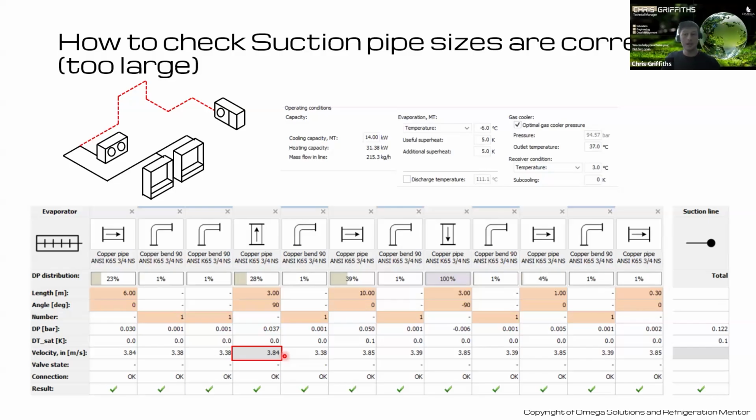At that point, we could introduce a double riser and have a second smaller riser coming off the top of it to return at part load conditions. For the sake of 3 fixtures, is that really worth it? Particularly on CO₂, I've designed a lot of CO₂ installations. I don't think I've ever had to use a double riser. It just doesn't happen in retail unless you have a huge number of fixtures only returning up a single point.